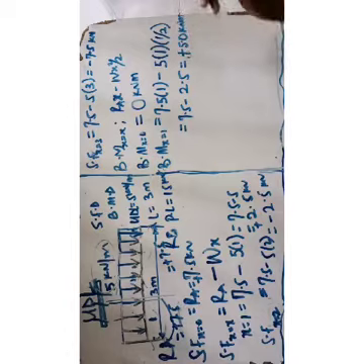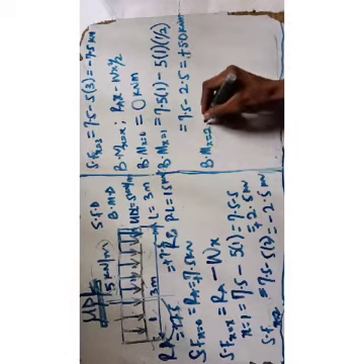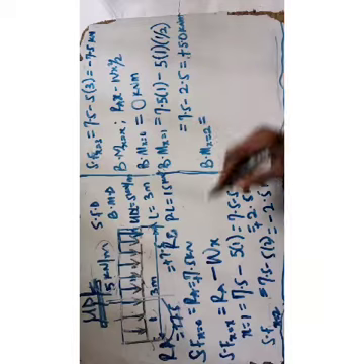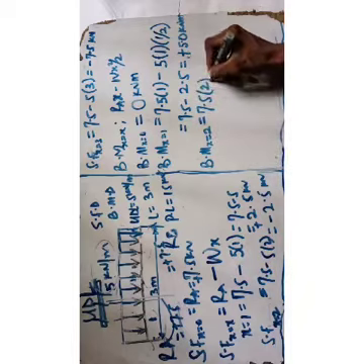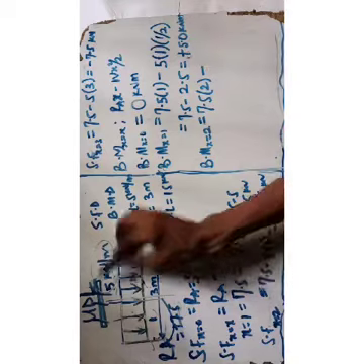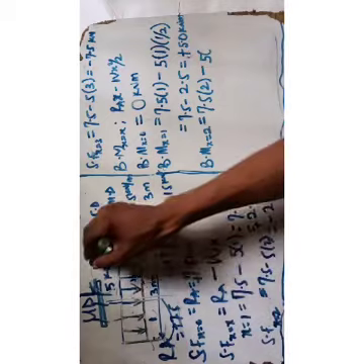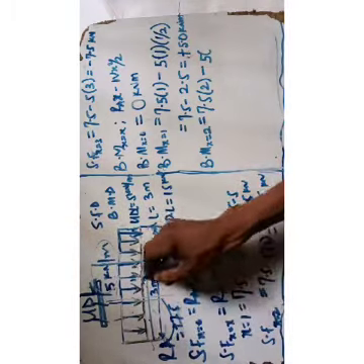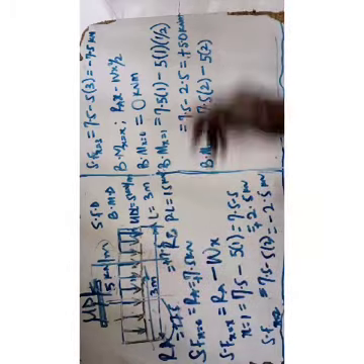kilonewton meter. So bending moment when x equal to 2 will now be equal to as well. Can you give that a try? So that will also be 7.5 times 2 minus 5 times the length you are taking, that is cross-sectioning when it is 2, that is when total length you are considering is 2, 5 times 2 times the half of that 2.